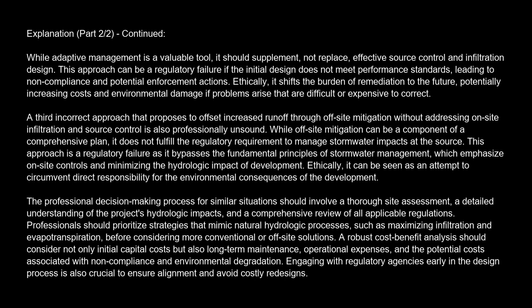A third incorrect approach that proposes to offset increased runoff through off-site mitigation without addressing on-site infiltration and source control is also professionally unsound. While off-site mitigation can be a component of a comprehensive plan, it does not fulfill the regulatory requirement to manage stormwater impacts at the source. This approach is a regulatory failure, as it bypasses the fundamental principles of stormwater management, which emphasize on-site controls and minimizing the hydrologic impact of development. Ethically, it can be seen as an attempt to circumvent direct responsibility for the environmental consequences of the development.